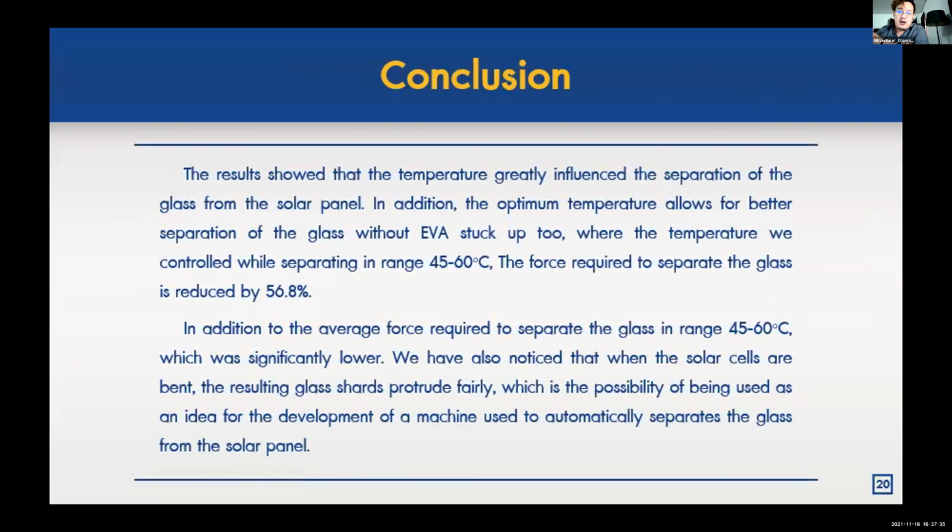So, two conclusions. These experiments demonstrate a prospective option to direct heat to the core of the PV panel using the microwave heating process. The results show that temperature generally influences the separation of the glass fragments from the EVA layers of solar panels. The dielectric heating of microwave involves the heating of electrically insulating material by electric loss without destroying the characteristics of silicon and other materials. So this process may enable different second life recycling processes of PV panels.